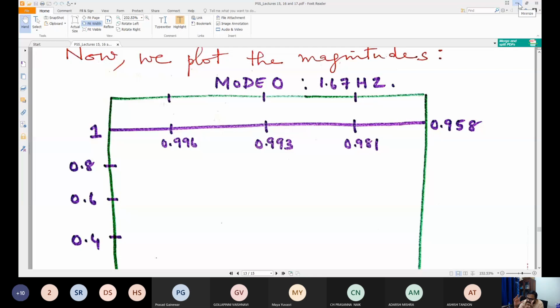more amplitude. The angular displacement is more for some modes. That means that the disturbance has affected more in that region. That means that region is prone to asynchronism, because basically these oscillations are in terms of delta, power angle delta, right? I'm not discussing torsional oscillations. I'm discussing multi-machine oscillations in the power system itself. Similar to that only, subsynchronous oscillations are modeled.